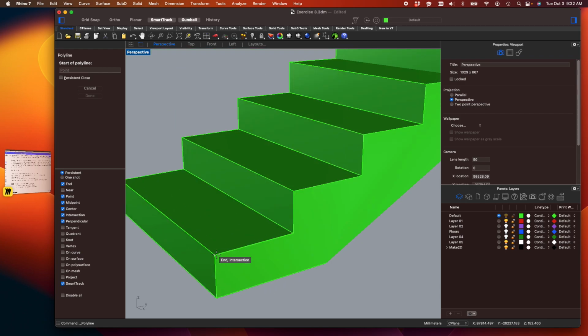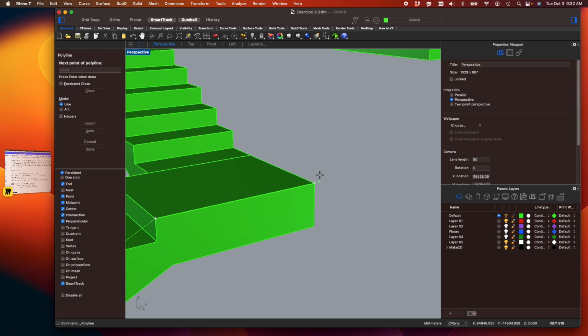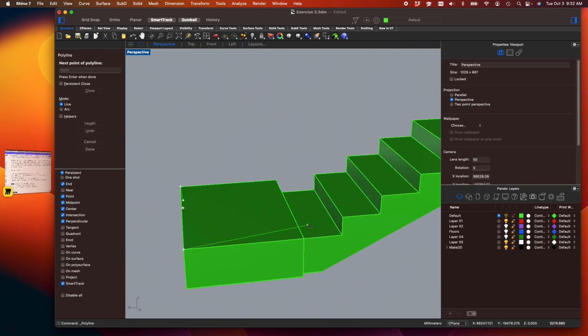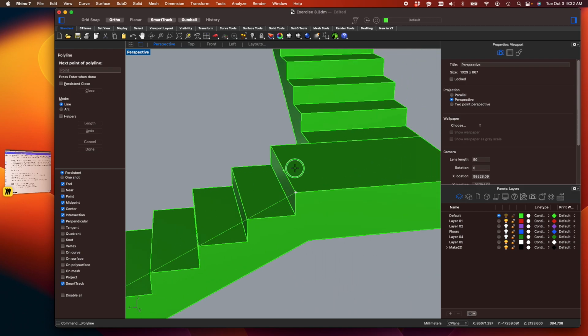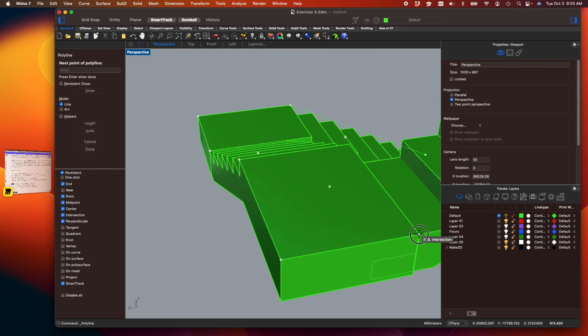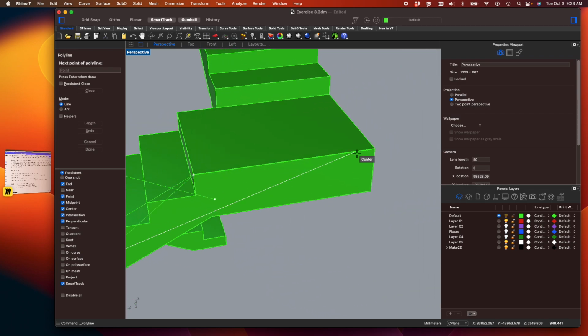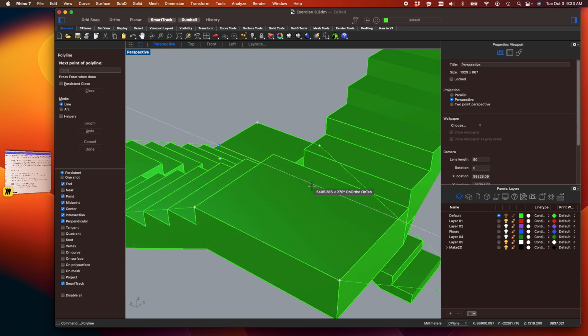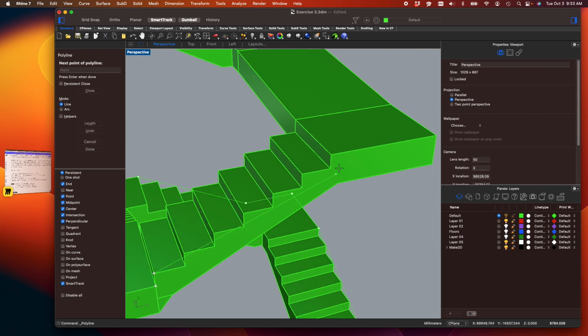So in my case, this is maybe the most time-consuming part. We basically need to retrace this edge. I do want a guardrail at the edge. I do want it to start here. I do want it to maintain that angle, so I'm basically just choosing the angles and choosing the perimeter of my landing. However, look at what I'm clicking on. I'm maintaining that angle and the flatness of those landings as well. In my case, I accidentally went up here, so I'll need to do both. There'll be a little bump in that one.